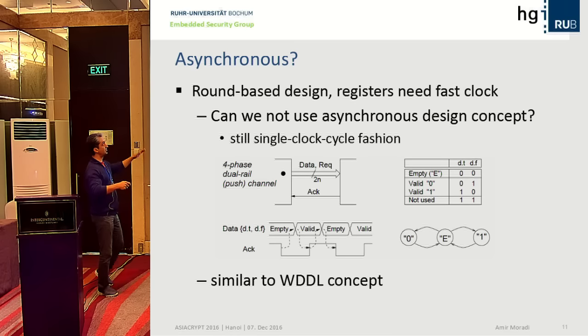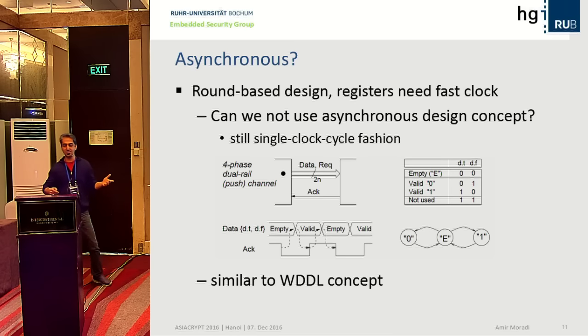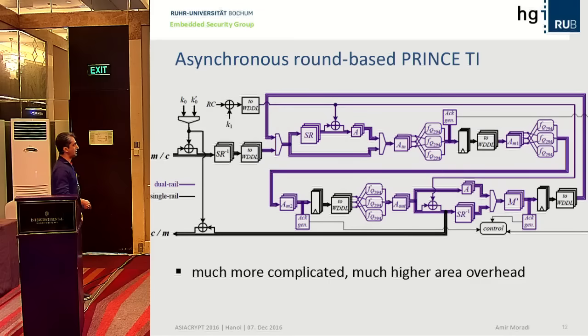The idea was to use asynchronous logic to avoid the fast clock in the circuit, and then see which achievements we have. If you are familiar with side channel logic styles, it's very similar to the concept of WDDL, which is wave dynamic differential logic, proposed in 2004 as a side channel countermeasure, actually for reducing the leakage of the side channel.